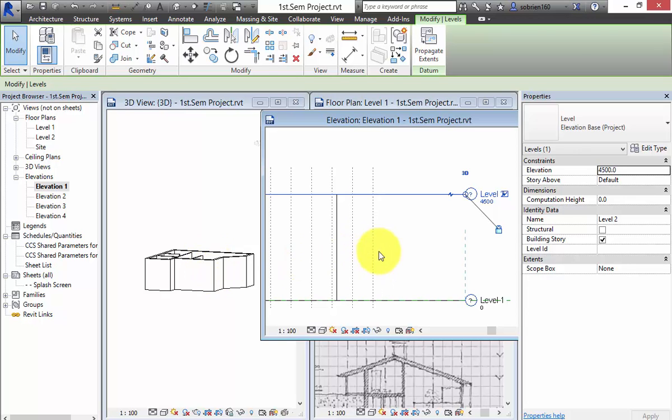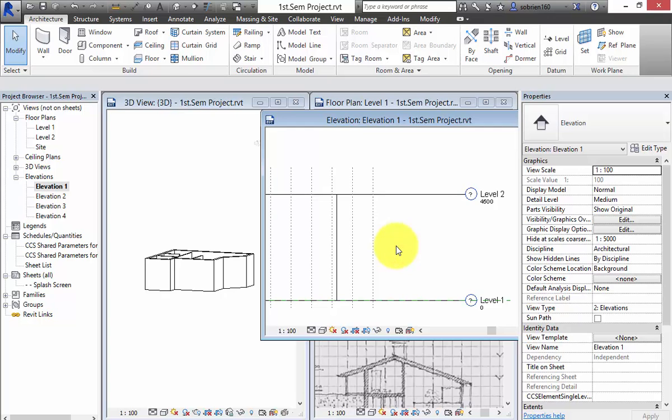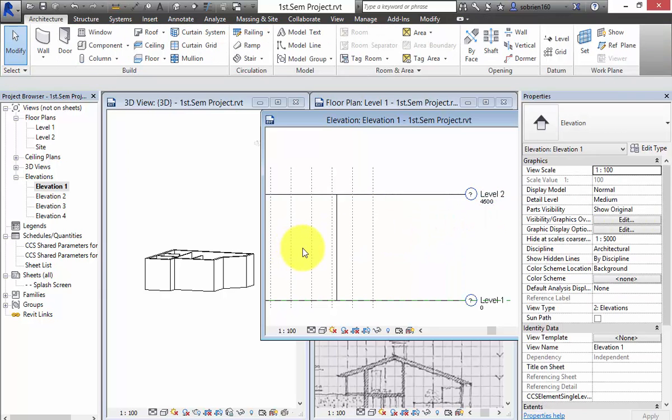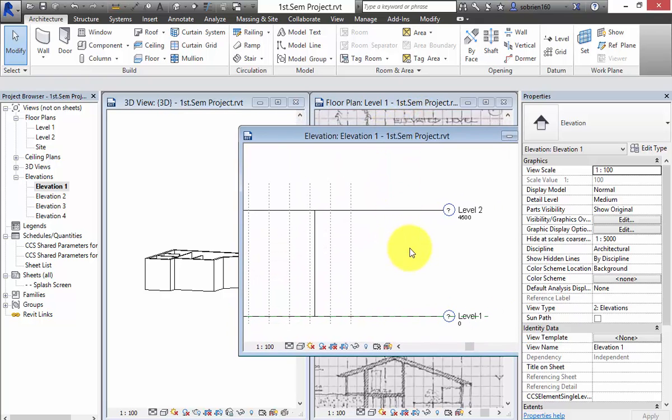So that's kind of the time saver on it. If you have a client who suddenly decides that they want this floor level to change, or you get to a point in the design where you realize you haven't made enough room for the pipes in the ceiling in your office building and you need to make the floor slightly higher, it's just a question of changing this value here, and everything else will stretch to take that into account. So if you're used to making hand drawings, or you're used to making drawings in AutoCAD where you have to redraw everything each time, this is thousands of man hours saved by just this single function. So that's something to remember.